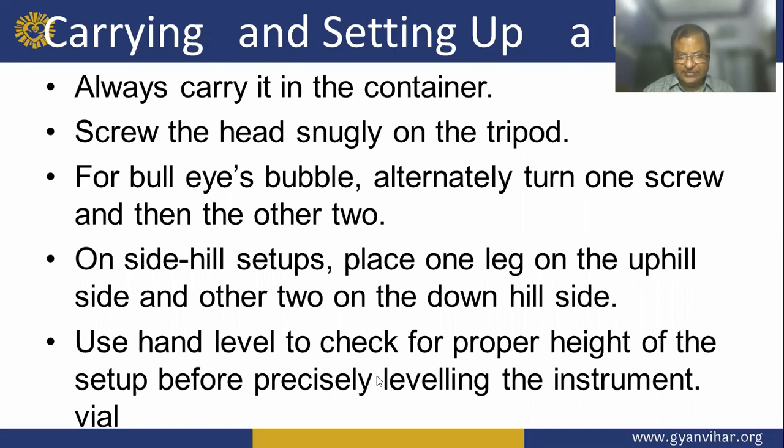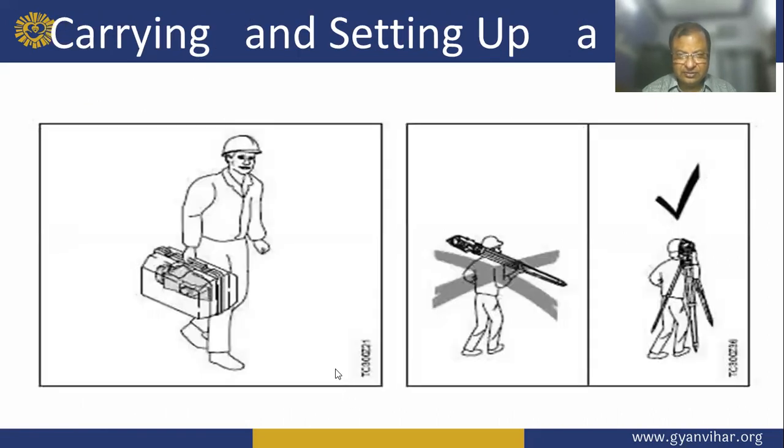Use a hand level to check for proper height of the setup before precisely leveling the instrument. So this is carrying and setting up of a level. This is the machine, this is the staff.